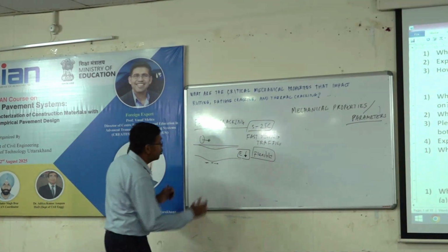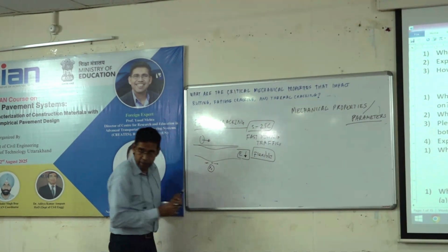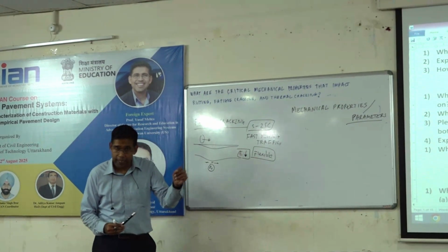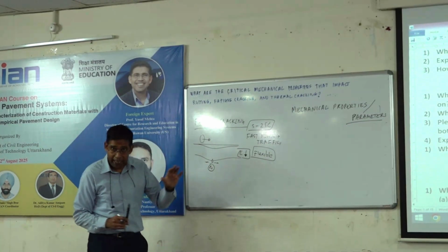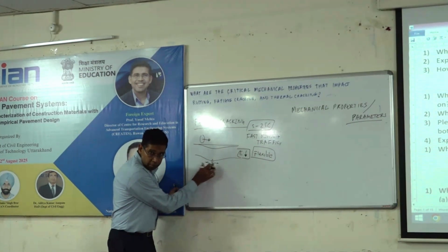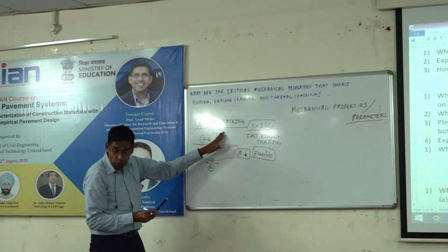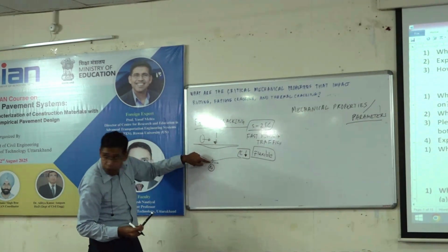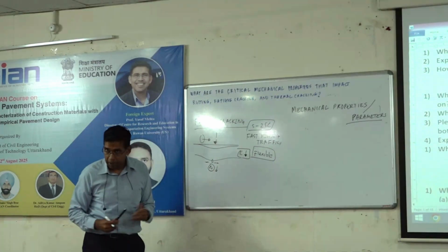Correct. So you have a certain tensile strain developed, right? Or a stress, and if this exceeds a certain brittleness or ductility, it's going to create a first crack. Everybody understand that, right? So there's a load. How can I minimize that? The load is on the top, correct? That's not in my control, the amount is not in my control, but I know what it is. So if I can move this point away from the top, I can drop the tensile strain. Simple beam theory. That's number one.